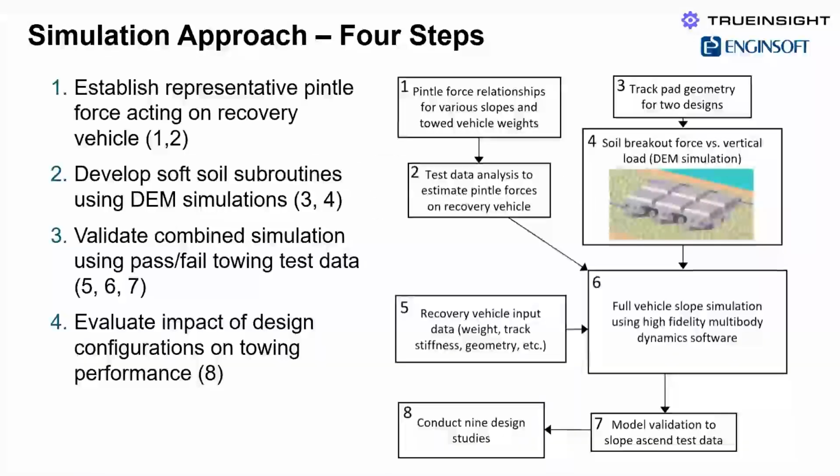So for this study, there are basically 4 steps, and those 4 steps are taken into account with these 8 different blocks here in the diagram. The first step is to establish what's a reasonable pintle force that might act on the recovery vehicle. The pintle force is really referring to that resistive force pulling back on the rear of the vehicle.